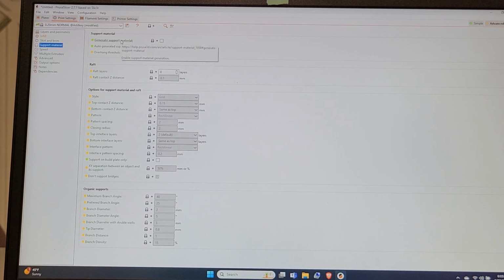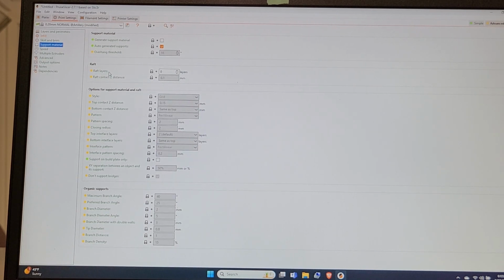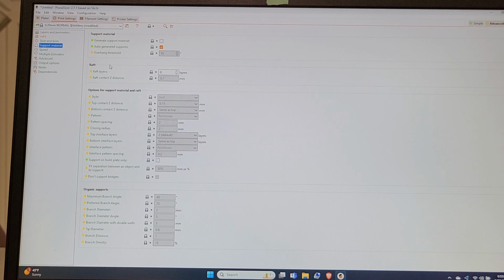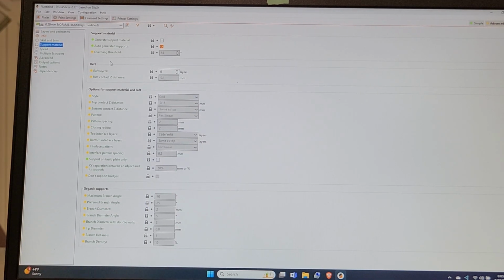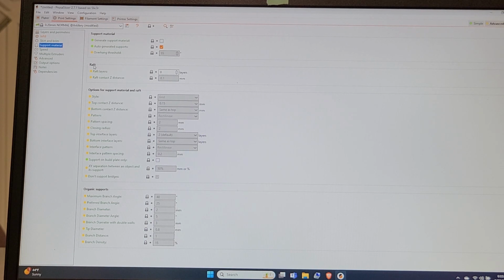And then if you're having to do spheres or a pyramid, like an upside down pyramid type, where the spot on the bed is going to be a lot smaller than the rest of the print, then you want to do a raft, and that'll help hold that in place. Some people end up using a raft to fix adhesion issues, and that's really a big no-no.